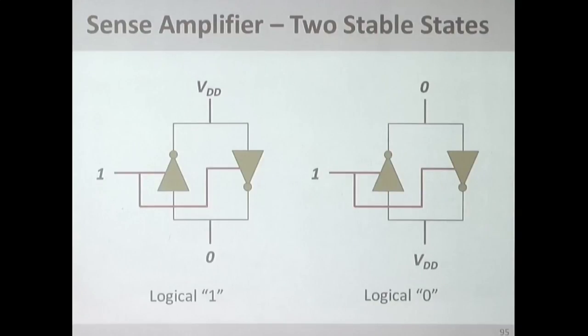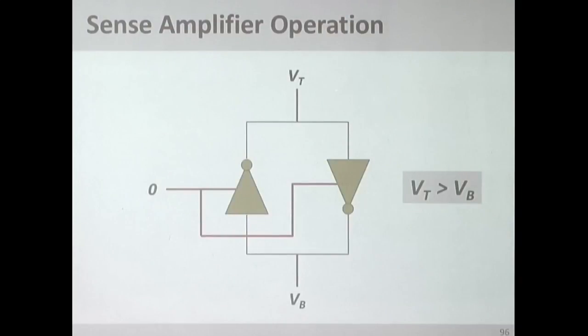And you connect either part to a bit line. So assume that this is larger than this slightly, higher than the sense amplifier threshold. This is a disabled sense amplifier. When you enable it, it basically senses this difference. And because of the feedback, amplifies this to VDD and amplifies this part to 0. Right? That's how it works.